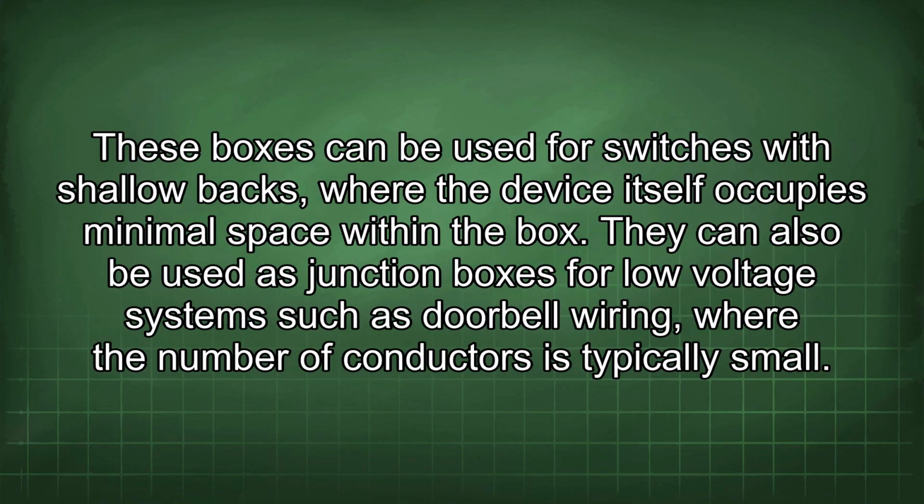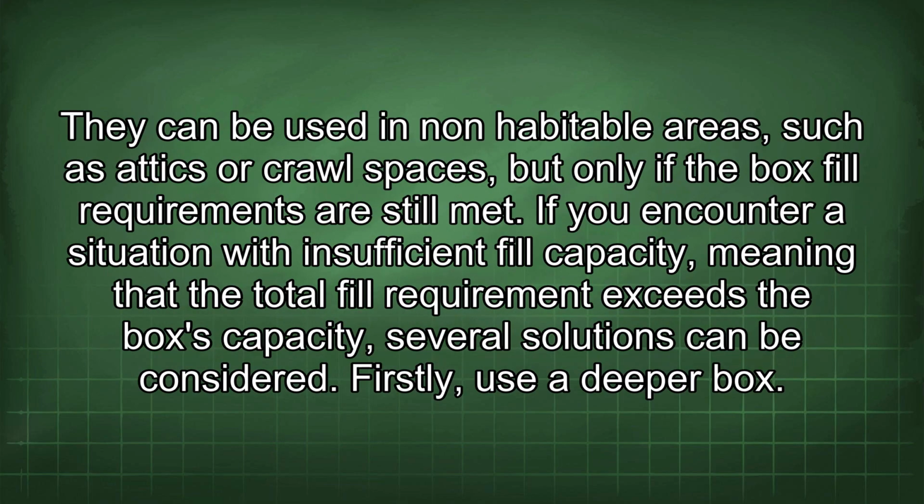These boxes can be used for switches with shallow backs, where the device itself occupies minimal space within the box. They can also be used as junction boxes for low-voltage systems such as doorbell wiring, where the number of conductors is typically small. They can be used in non-habitable areas, such as attics or crawl spaces, but only if the box fill requirements are still met.